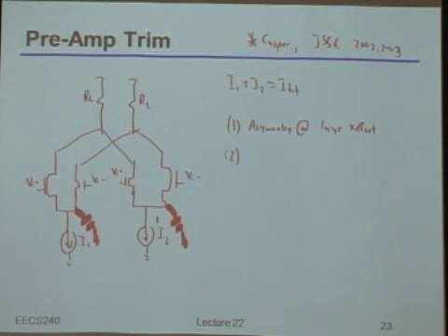So you asked a very good question, which was, are you trying to cancel the offset of this or the comparator that follows it? You guys tell me. What are you trying to do? Both. Isn't the range not V star? It's like V star times GM times the gain of this? GM times the gain of this. So I don't think the units of that quite work out because that's a current. I mean, you're trying to cancel, like the comparator offset is a voltage offset.